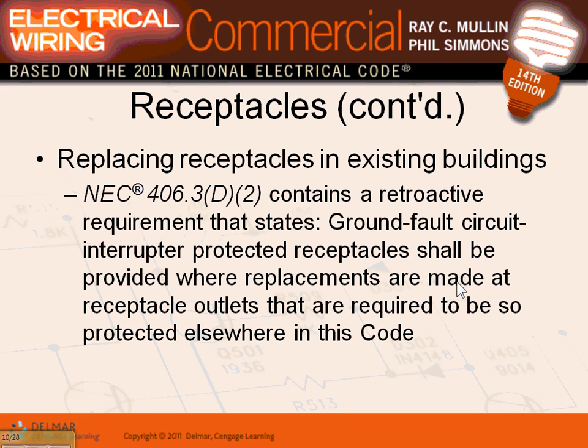Receptacles in existing buildings. This will tell us, guys, we rarely get into a commercial building and change it. If it's a commercial building and it doesn't have a ground, if you ask me, go rewire the whole building. This is mostly for residential. You walk into a house and it's not grounded, there is no equipment grounding conductor. So you are allowed to replace the non-grounding receptacle with a grounding type receptacle, GFCI.